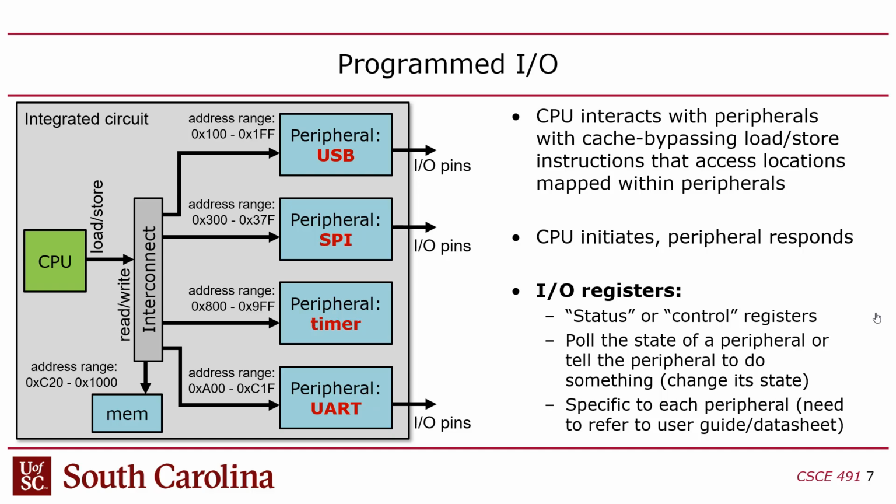So the CPU sends workload to the neural processor on the Apple chip ultimately through programmed I/O. That's how it initiates the NPU. The NPU does number crunching, and then it triggers an interrupt and tells the CPU when it's done, right? So when you do your Face ID, for instance, on your iPhone, that's what's happening: you're offloading work to a peripheral, but that peripheral is on the same chip, right?